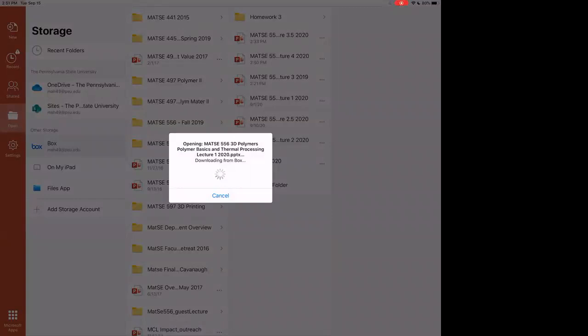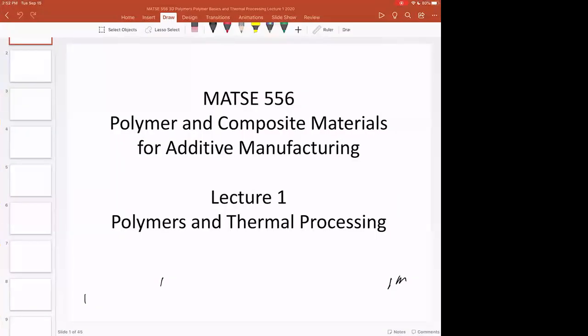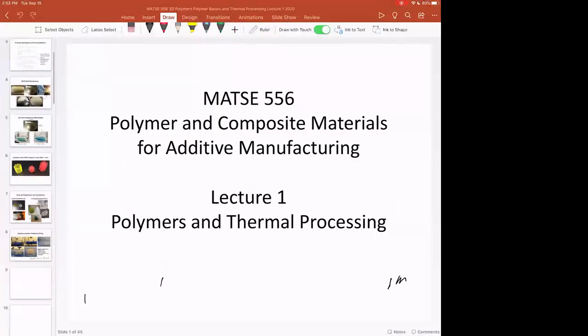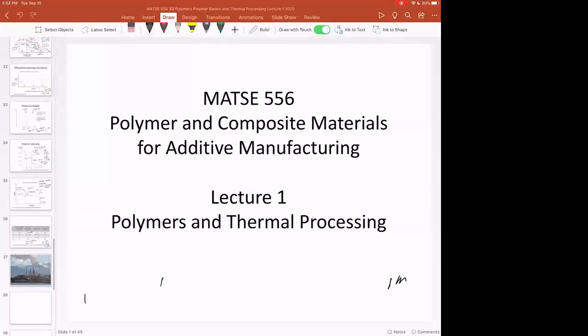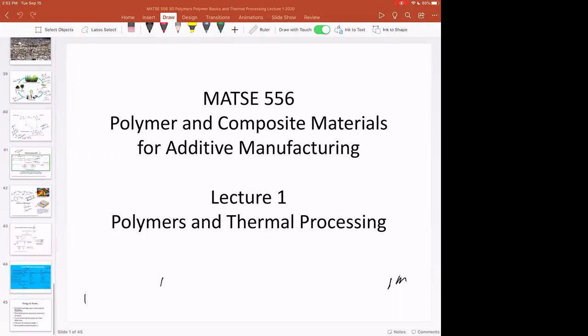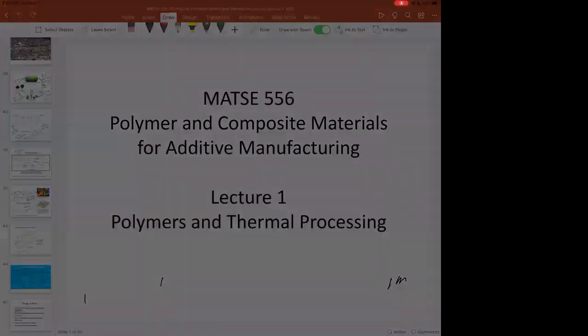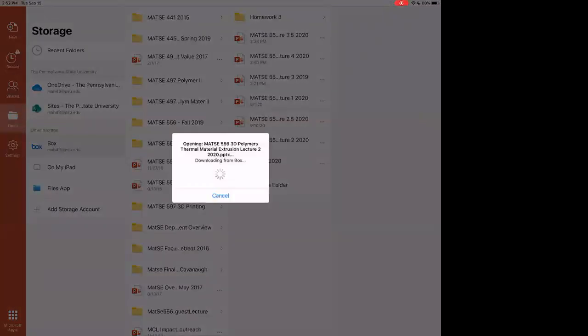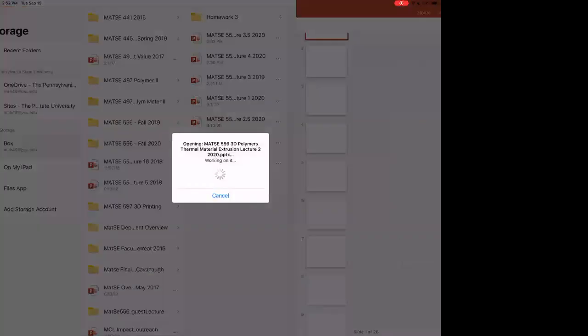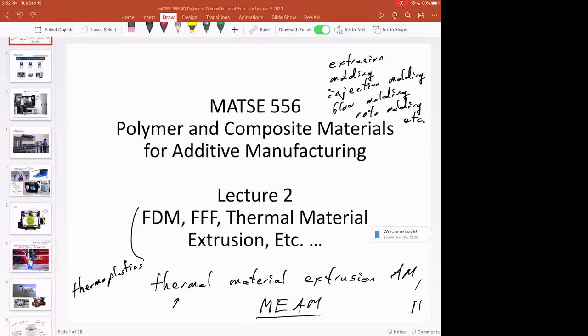And also, additional to that, having the distance very far apart, instead of just benefiting it to make that perfect cylinder, would also be a bad thing, right? If the distance between the layer height and the nozzle was very separated? Yeah, if the layer height is too high, you won't get any compression, and you won't get any adhesion between the different layers.